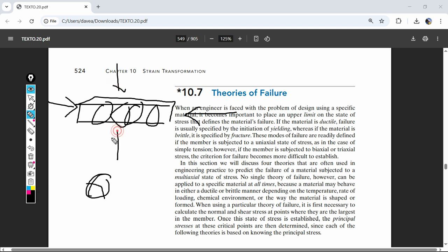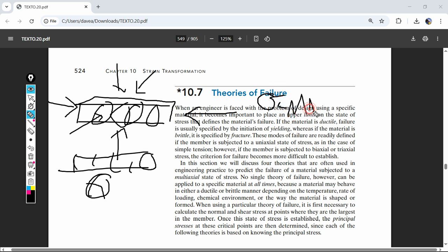If I have these pressures in three directions, due to these straps holding this thing together, think of it maybe as a circular dowel with steel straps around it. Then maybe the sky's the limit, because this compression doesn't get maxed out. If you're compressing it on all sides, you can actually go way higher than this.